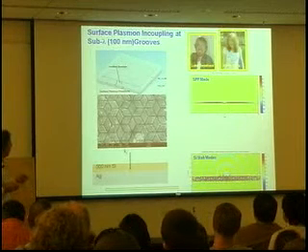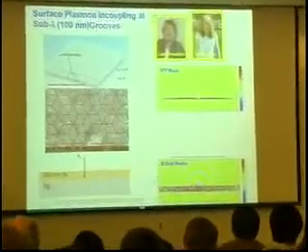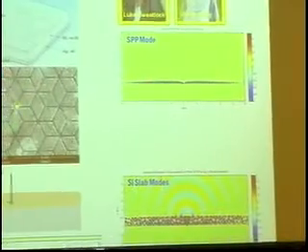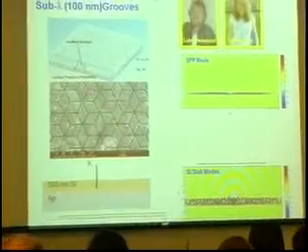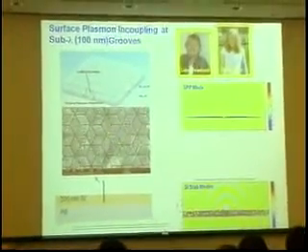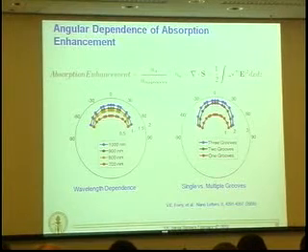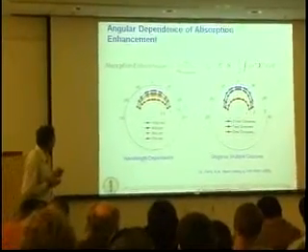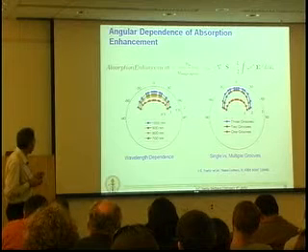And so you can see here the modal confinement characteristics are very different depending on the mode. And they have different fractions of absorption in the semiconductor and the metal. One of the things that's interesting about these is that if we corrugate, if we create particle arrays or grooves and bumps on a planar metal surface that are sub-wavelength in character, these sub-wavelength particles act as dipole scatterers. And dipoles have a broad spectral acceptance for excitation. They, in fact, do generate polarized absorption and emission, but it's spectrally broad.